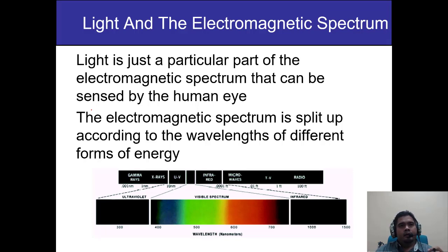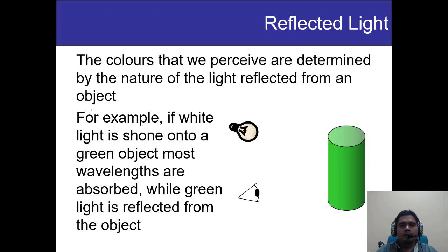So in that part, the intensifier has a characteristic where it converts that X-ray electromagnetic spectrum into visible light electromagnetic spectrum, and that visible spectrum is actually an analog image. The end part of the intensifier is a CCD camera, or I'm sorry, a CCD sensor, which converts the visible spectrum, in the form of an analog image, into a digital image. So this is some basic understanding.